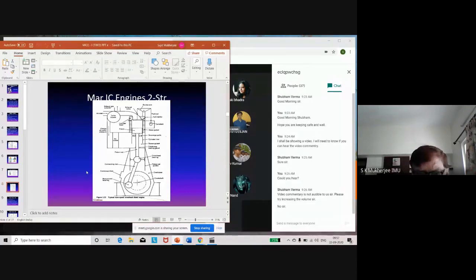In time, when I get a chance, I will draw the diagram and show you how an oil wedge formation is required to enable hydrodynamic lubrication. But remember, for any bearing, any journal bearing in particular, four parameters are essential. Number one, viscosity. Number two is the speed of the shaft. Number three is the clearance within the bearing. And number four is the load. You cannot afford to overload. It has to be within the design load.